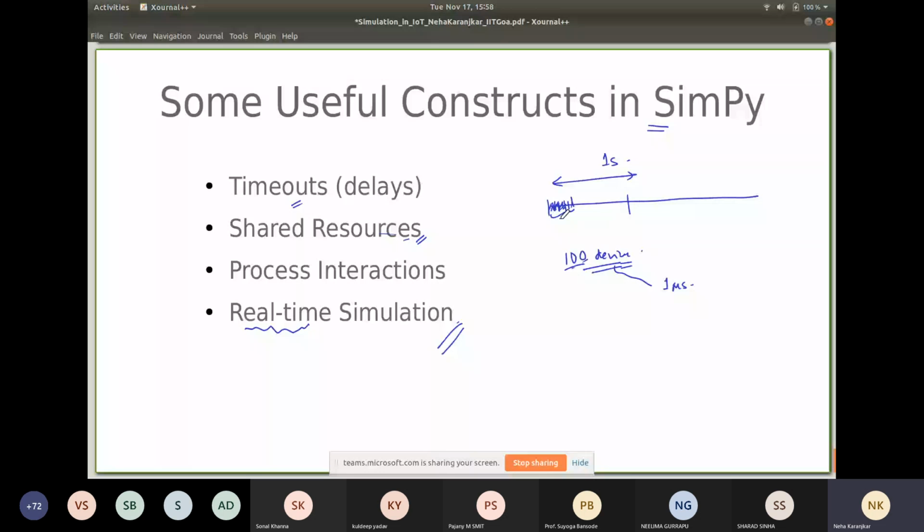So the remaining time the computer just waits, does nothing, it's idle. And after 1 second, again you simulate the behavior of the devices. This is to keep it in sync with the time specified, so it's actually real time. You say that the sensor should wake up after 1 second, so to keep it actually 1 second, you do nothing. But if it's a normal simulation, not real time, then whatever time the computer takes, at this point you will update the time variable and say t is now 1 second.